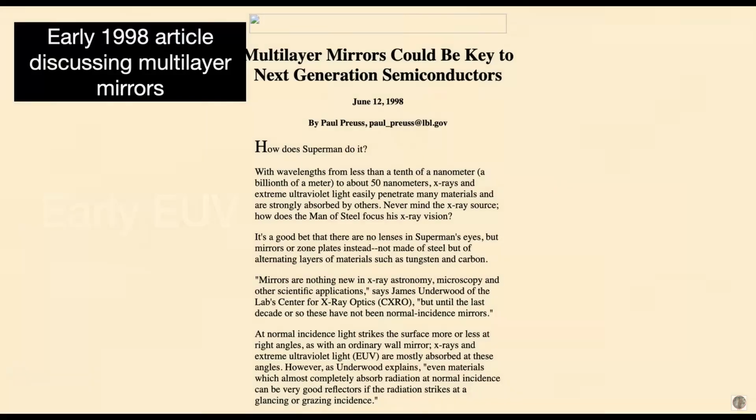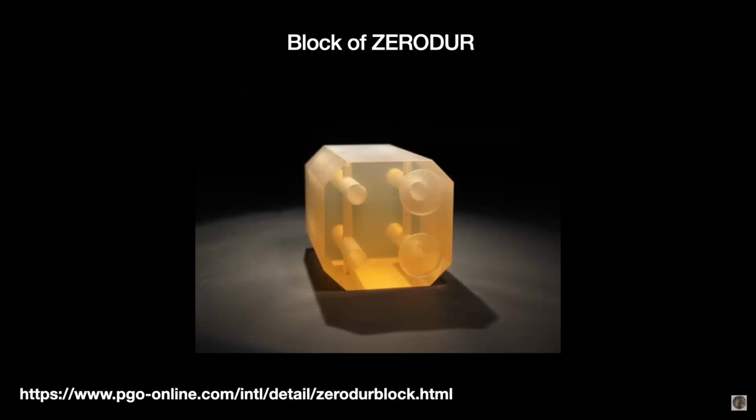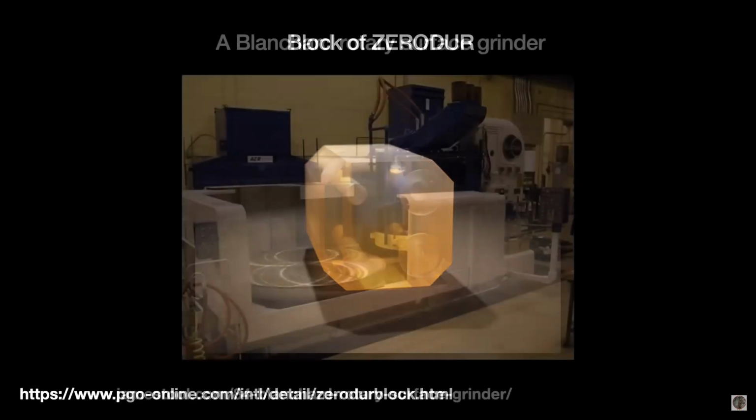In 1992, Kinoshita at NTT Labs brought in the American lens maker Tinsley, subsidiary of the lithography company SVG in California, to produce a new set of mirrors. Mirrors in this prototype EUV era were aspherical, meaning that they were not perfectly spherical. They were made in a progressive four-step process that Tinsley had been researching since 1990. Starting with a substrate of Schott's low thermal expansion glass ceramic Zerodur, the mirror blanks were first machined flat or to an initial geometry using Blanchard rotary grinders.